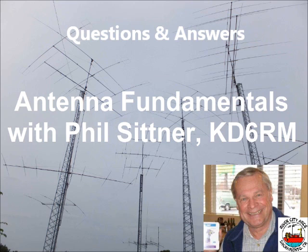Everybody here seen a ground plane antenna? That's the one little vertical element with the spokes coming out underneath it. Well, as you bend those spokes up and down, you change the input impedance of the antenna. You can get it exactly 50 ohms by bending them up and down, because you're changing the relative relationship of the ground plane to the driven element. And that's your ground plane, not the ground.